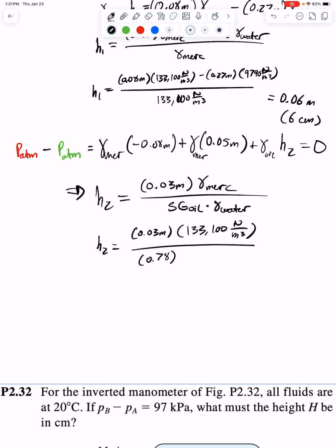Yes? Go from rho to S times gamma water. You mean gamma? There was in the question you just solved last. You mean this part here? Denominator. Yeah. So I think what you're saying is how do I get the gamma for the oil, right? Specific gravity, that we're given, refers to the ratio between the current specific weight of your fluid compared to water.